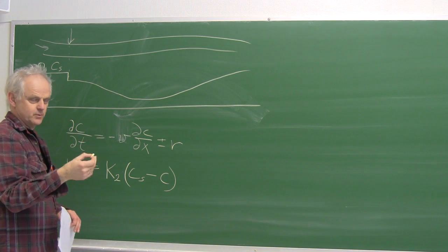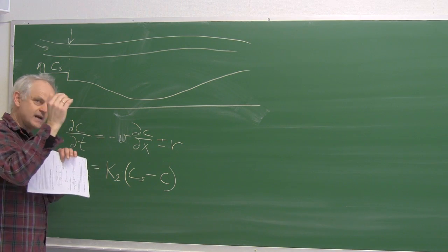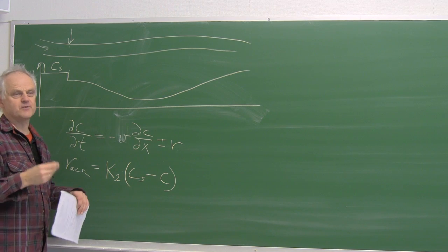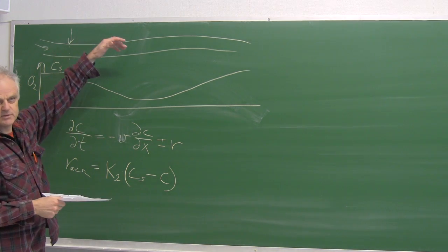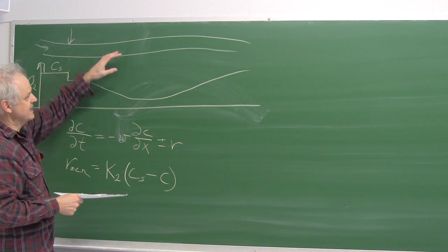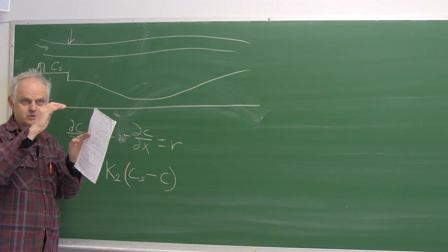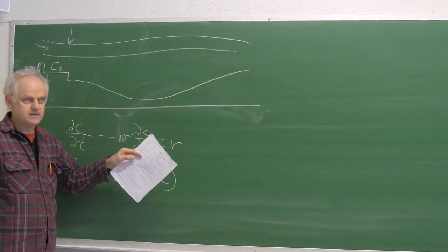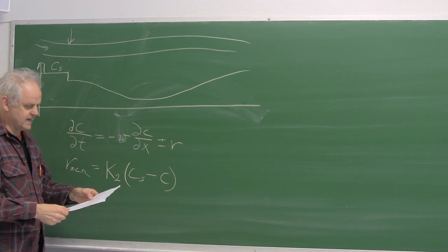That is what you will see if you go into the theory. The area between gas and liquid is the main thing, and the area in the river depends, for instance, on how steep it is. If it's steep, there are more waves, so you get more surface for that reason. But if you have a really narrow and deep river, it has small surface area to volume, which will give a low value. If it's wide, then you have a high value. So these things all influence it.